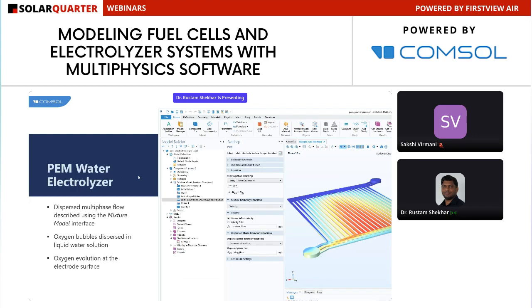You can use it, let's say, in some cases where you may not be interested in the electrochemical performance, only the flow profiling for PEM fuel cells, because in PEM fuel cells flow is more important compared to the electrochemical setup, because there you are dealing with a multi-phase system, available in free and porous media. So you are dealing with a system where you want to maintain the temperature, you want to operate with two different phases like liquid and gas, and that too in free and porous media. So that will give you a very complex flow system.